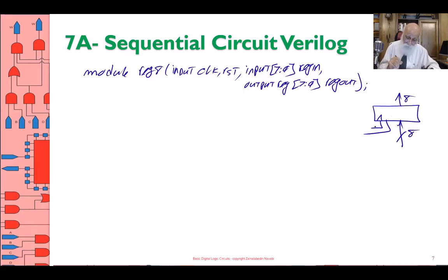Let's start with this. So you say always at posedge clock. Let's do asynchronous as I'm showing on the right. Posedge. Let's do negedge. Let's put the bubble. Negedge reset.